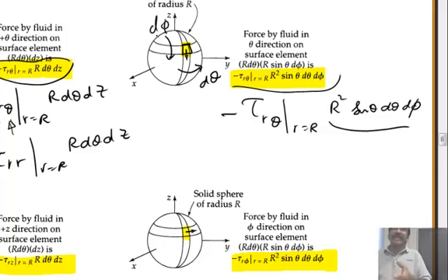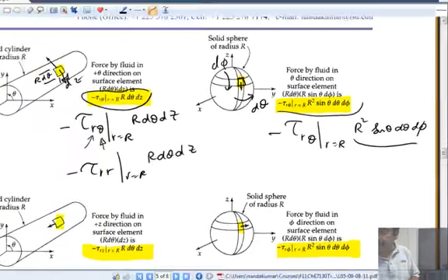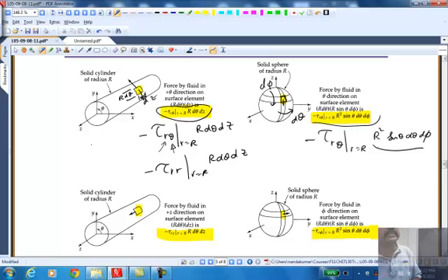This is the momentum transfer due to molecular interaction in the r direction on the r surface. So this is part of the stress component, but there is a component that also acts normally to that, separate from pressure. It is, you already recognize that tau r r must be normal to that particular surface. But that is not the pressure. Any other questions?